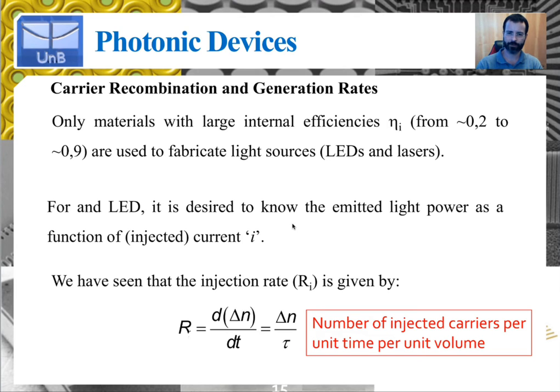So what you usually have is a directly polarized diode, right? Of course, you must have a current limiting resistor of some sort, but just in a simplified picture, you need a directly polarized diode in which the direct current, due to the recombination inside the active layer of the diode, is going to be responsible for making the spontaneous emission process possible.